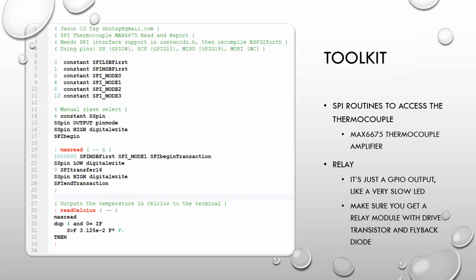So we step into the next thing. One of the things we needed for the project is actually also SPI. So SPI in my interface as exposed, you will need these constants that will help you. It's basically an expression of the built-in Arduino constants, and then you must specify your own slave select, of course, and set it up.